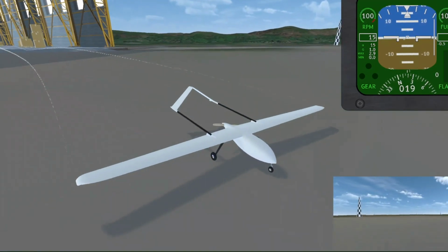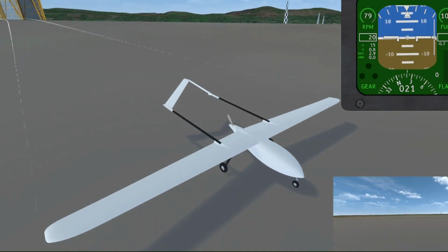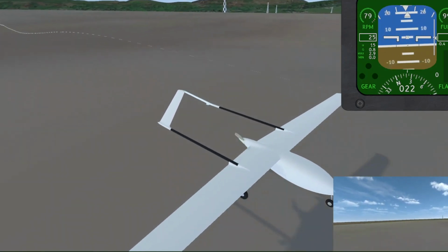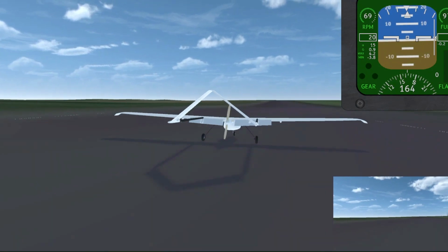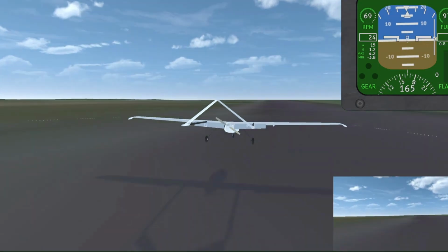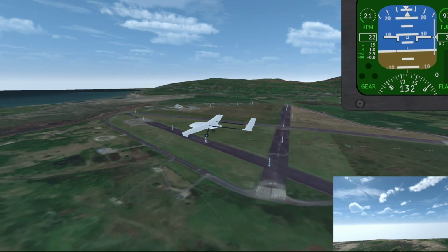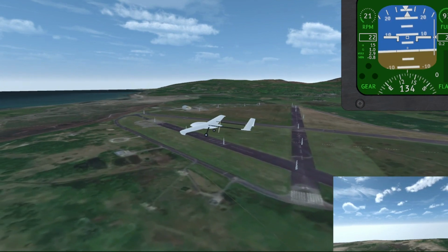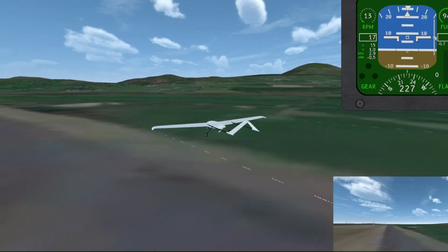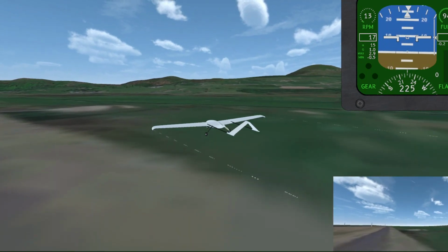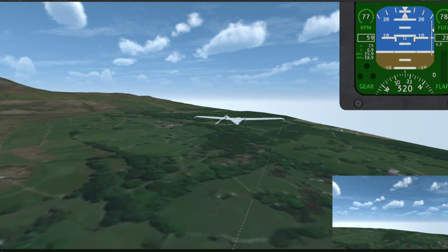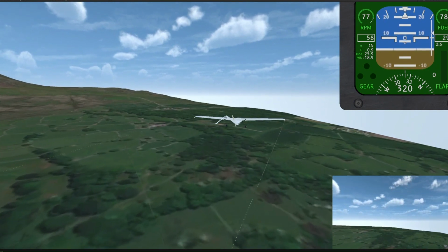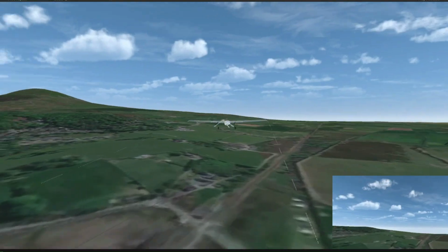The minimum speed needed to achieve wheels off the ground is about 23 meters per second without flaps. With flaps, this is 21 meters per second. This is much greater than the predicted 10.5 meters per second stall speed. At 25 degrees trim and 22 RPM, cruise flight can be achieved at roughly 20 meters per second. With an elevator trim of 40 degrees, the minimum steady level flight speed was 17 meters per second. The maximum steady level flight speed was roughly 58 meters per second, requiring just negative 1.9 degrees elevator trim.